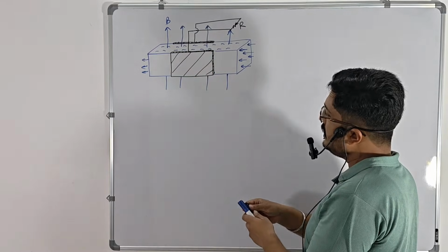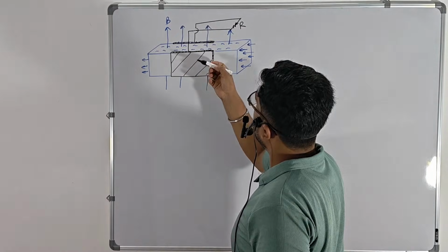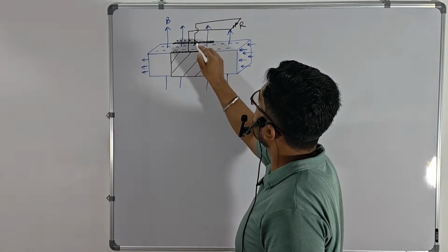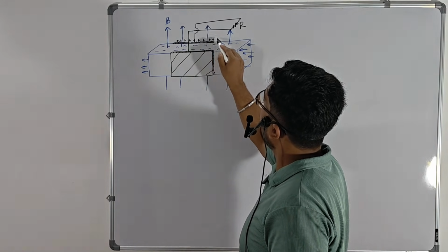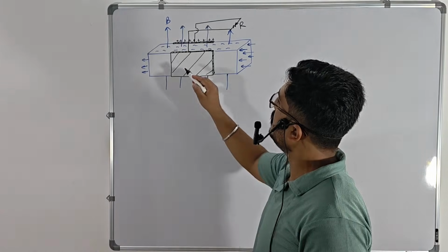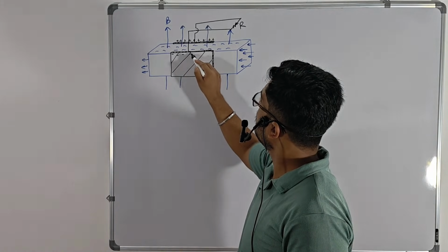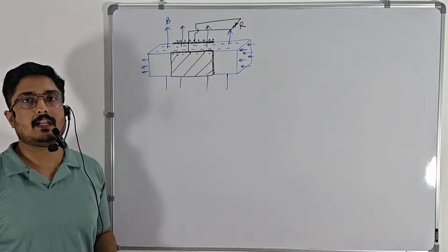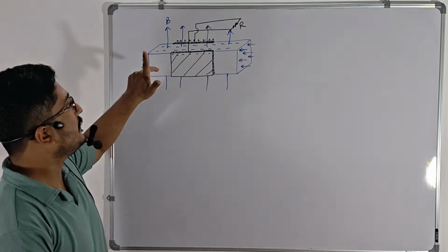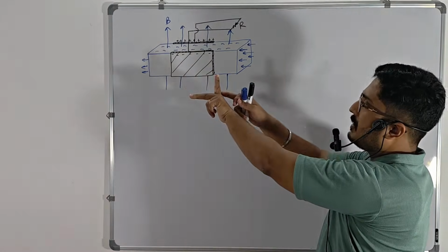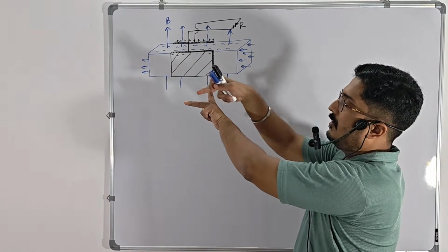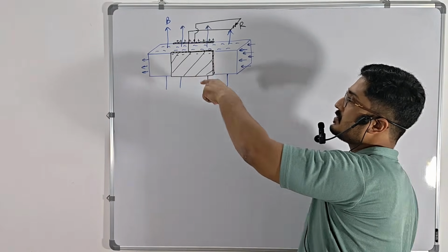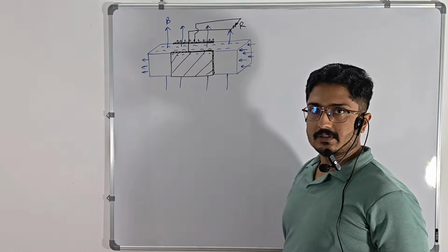Inwards means any fluid which is moving in this direction, the positive charge of those fluids would be accumulating on this side of the plate, and all the negative charges would now be accumulating onto this side. Whichever direction the positive charge experiences the force, opposite to that the negative experiences. So this is how the motion has happened: the magnetic field upwards, the conducting liquid moving in that direction, and the force experienced in this direction, with positive on this side and negative on this side.